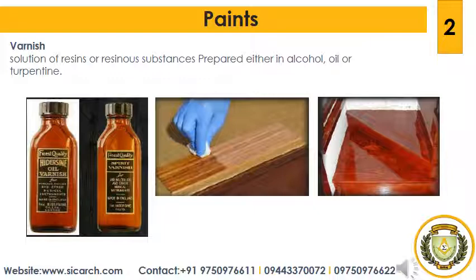Solvents. Depending upon the nature of the resin, the type of solvent is decided. Next we will see some solvents which are used for resins. For boiled linseed oil, it is amber and copal. For methylated spirits of wine, it is lac or shellac. For turpentine, it is mastic, gumdamar or rosin. And for wood naphtha, it is cheap varieties of resins.